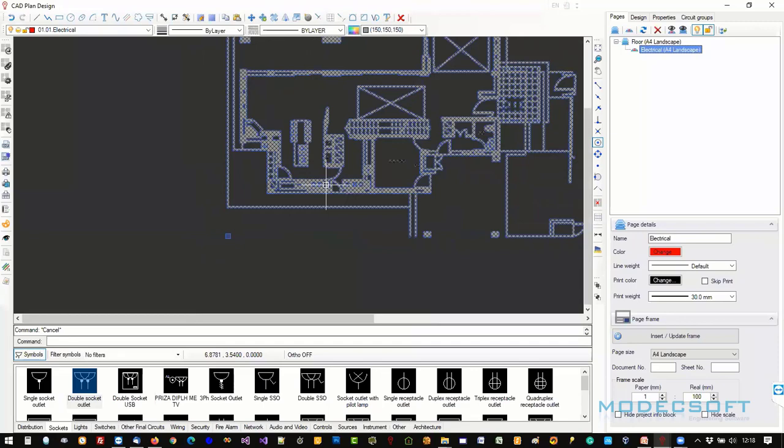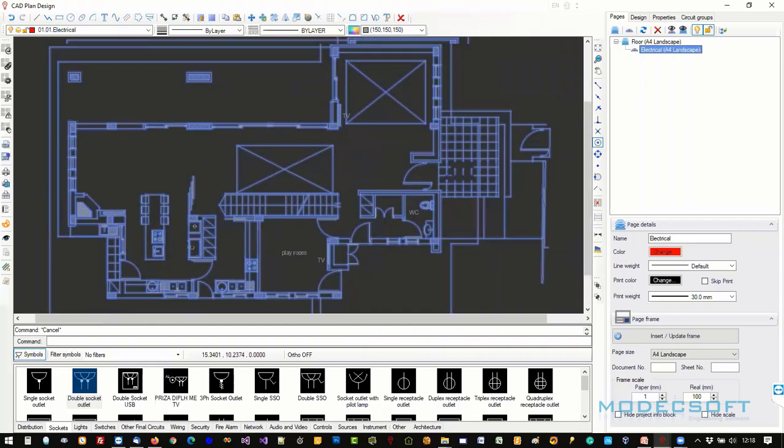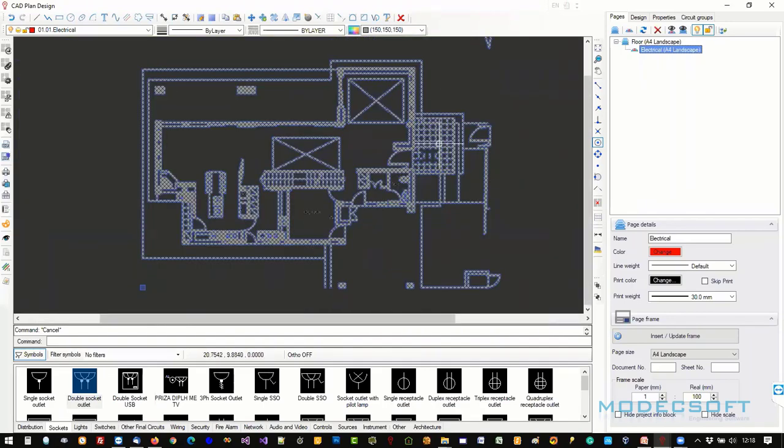It's one figure. Okay, so in case you would like to make adjustments in this drawing, you can't make them the way it is right now, because this is a reference drawing. So you have to go to your CAD editor, do the adjustments, and then reload that external reference into the plan design. Or you can bind it. Okay, so binding this drawing means that you will lose the reference. You will lose that unified entity, and it will be converted to individual figures.